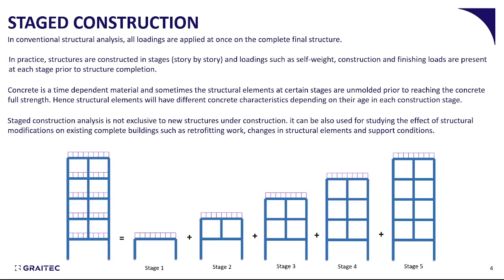Additionally, concrete is a time-dependent material, and sometimes the structural elements at certain stages are unmolded prior to reaching the concrete's full strength. Hence, structural elements will have different concrete characteristics depending on their age in each construction stage.